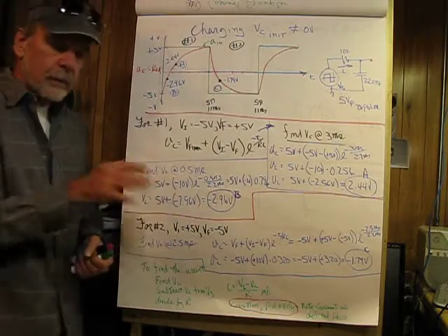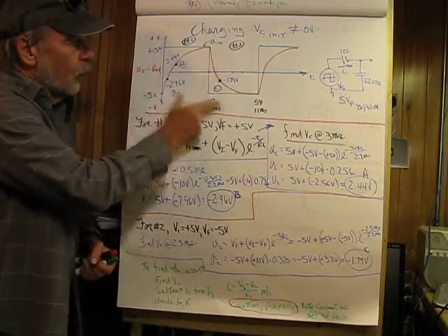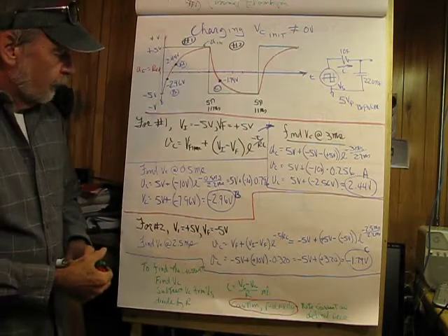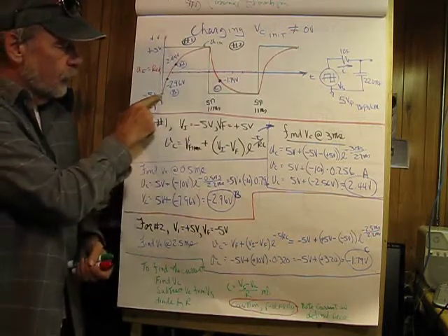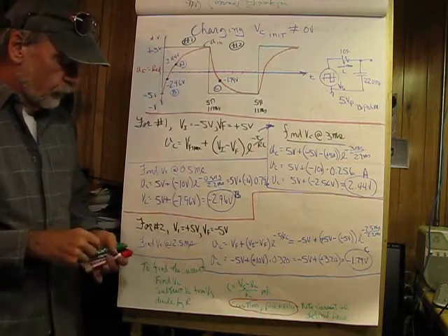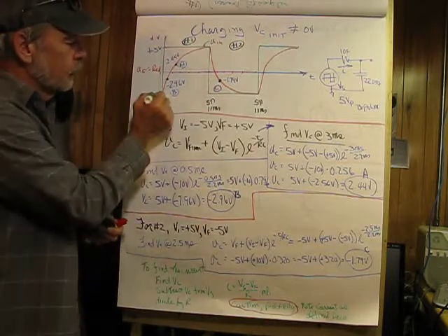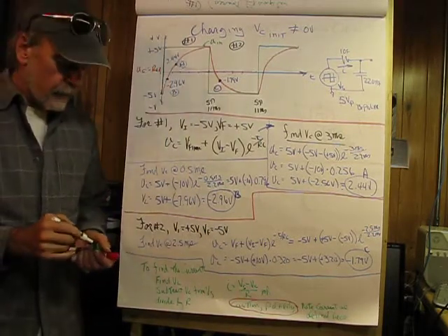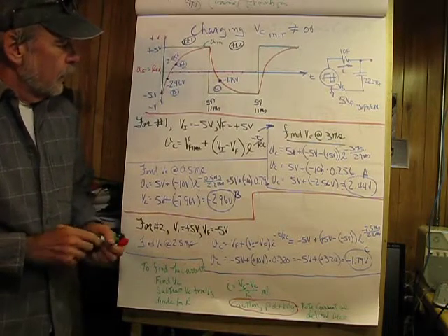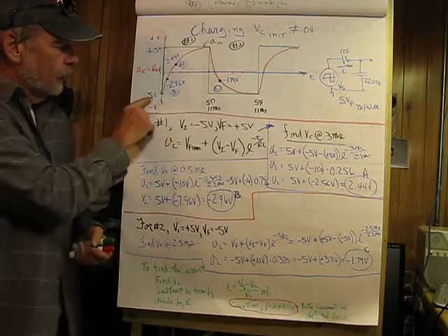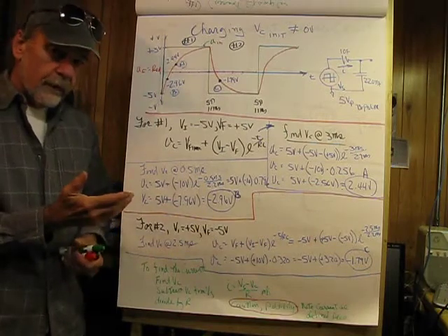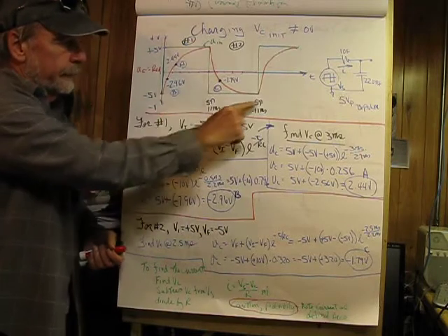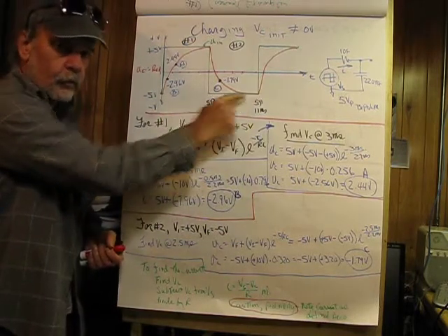Again, we're going to do this in pieces and look at number 1, and then we're going to be looking at number 2. So for number 1 here, our V initial is going to be -5 volts, and what we see in green goes from -5 volts to +5 volts. That is our starting point here. Our VC, the voltage across the capacitor, is going to be -5 volts, because this point is kind of like the end of this point. So this is where we're starting out.